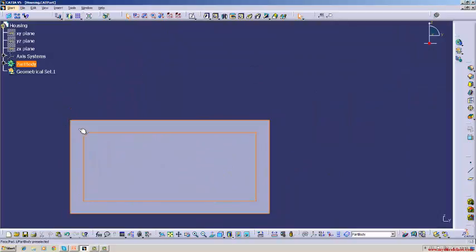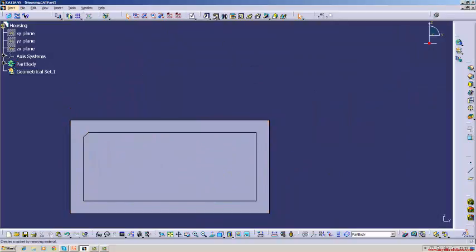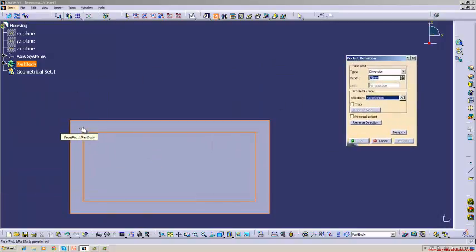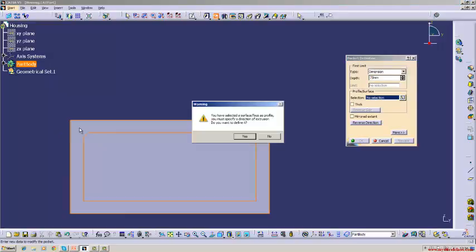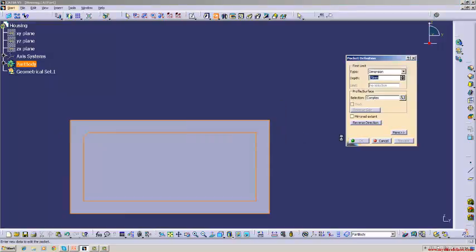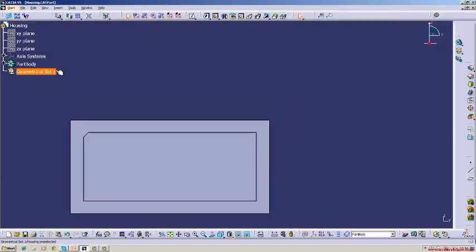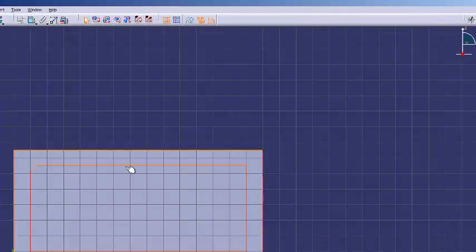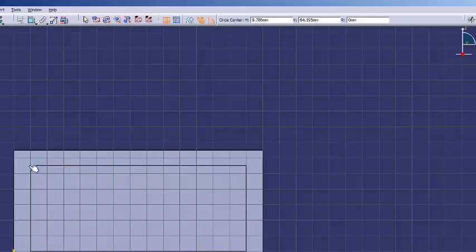I want to make a hole on the face. Select pocket command. But you have to go to the sketch plane. What you have to do is select the Y plane, a separate one. Now you draw a sketch here. This diameter you can click, you can give a diameter here.